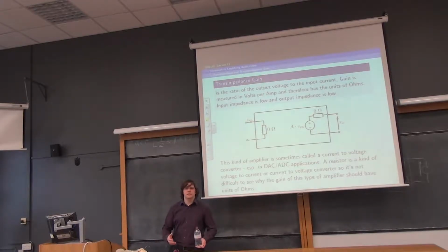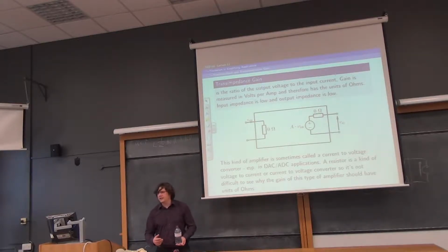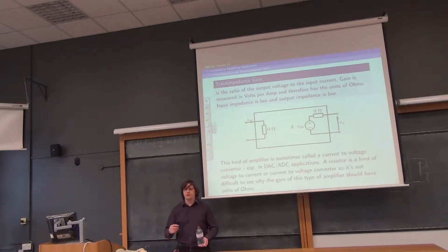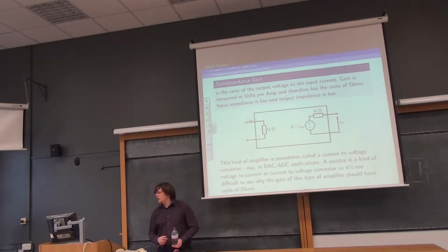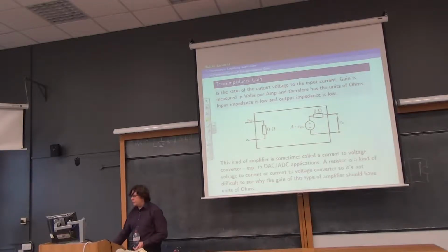So that's basically just a regular PN diode for the most part, except that we're not producing a current by forward biasing it. You reverse bias it, put some light in, and the light produces the carriers for you by an exchange of energy between photons and electrons. So we plug our photodiode into our transimpedance amplifier, and that would turn the current that leaves the photodiode into a voltage for us. And these are pretty commonly integrated into pretty much everything that has anything to do with fibre optics. It's got half a dozen of these sat in it somewhere. And you can buy them as integrated modules.